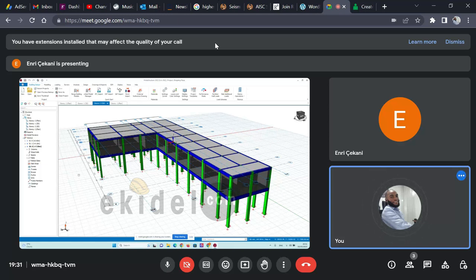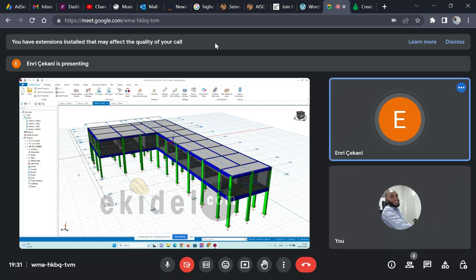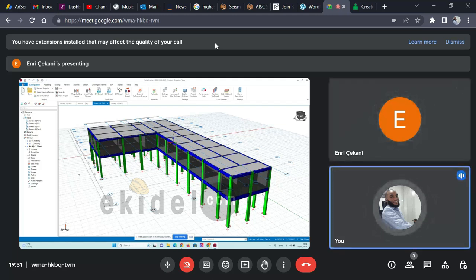Regardless of the intensity of the earthquake, the force of the non-ductile elements must not be more than that of the ductile elements. So what I mean is, regardless of the intensity of the earthquake or what you're designing, if you're using a diameter bar of 20 for your beams, you must not use a smaller diameter bar for the columns. So the strength of the ductile elements like columns must be higher than or equal to the non-ductile elements. I don't know if you get what I mean there. Okay, yeah, understood. So this comes into play when you're doing your detailing.